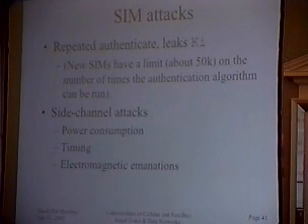Okay, so the repeated attack was public several years ago. One of the changes that SIM manufacturers have started to do is put a limit on the number of times you can actually run the authentication algorithm, which kind of puts a damper on the first method of pulling the SIM out, or pulling the KI out. That's not the only attack that SIMs are vulnerable to. There are side channel attacks that actually work for a variety of smart cards.